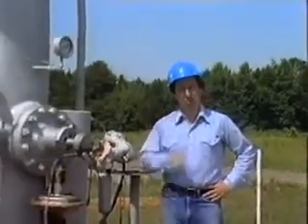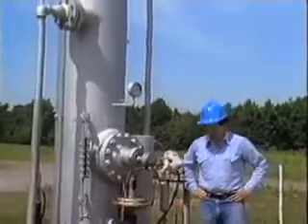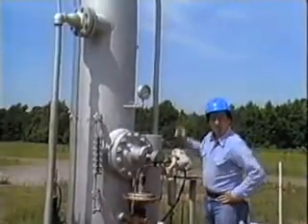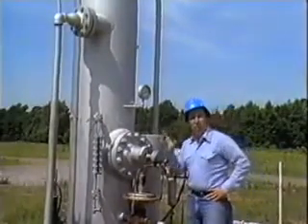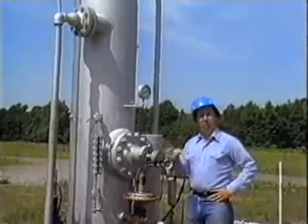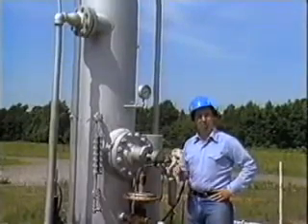On the job, you may hear separators called traps, knockouts, scrubbers, filters, and flash, or expansion chambers. These names are all applicable since they correctly describe various aspects of separators. So don't be surprised if you hear them. Whatever the name, this vessel is used to separate well stream liquids from gas components and debris.